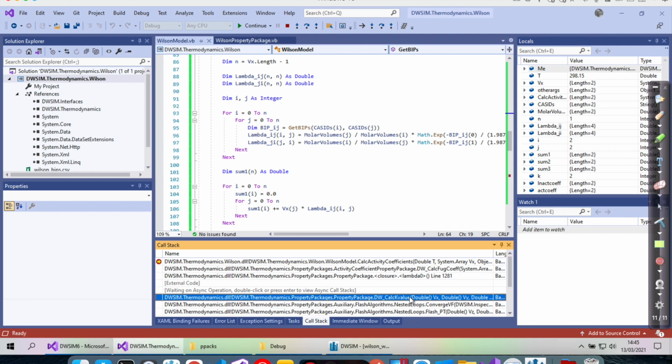This is easy when you simulate in design, because by default you say what you have at each stream. But when you are using plant sensors, you may have at the bottom 1 degree more than what is expected at the equilibrium, and then you are flashing the stream with, in practice, liquids, just because the error came from the sensor and not from your model.